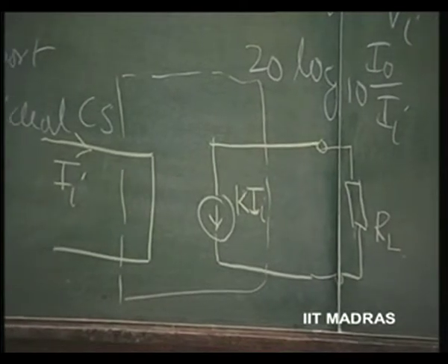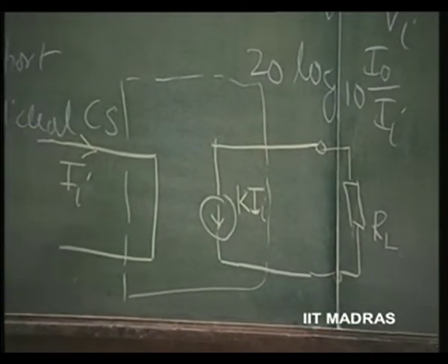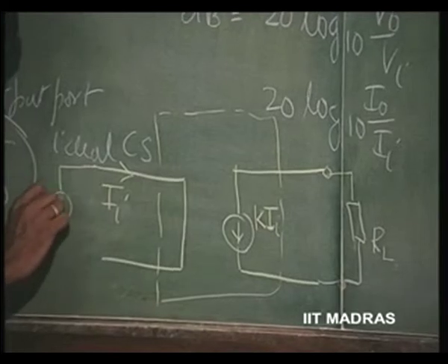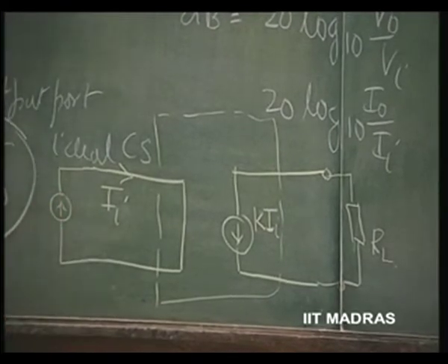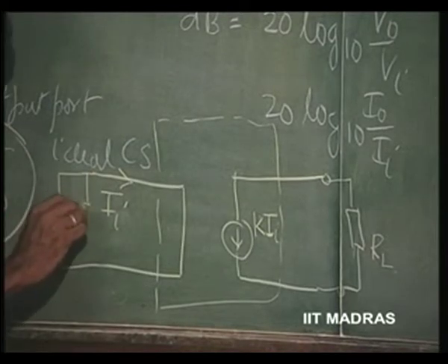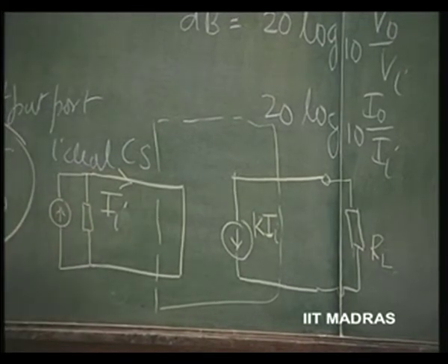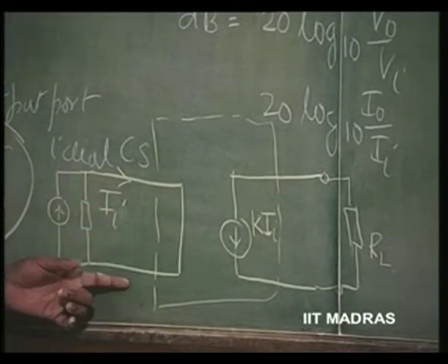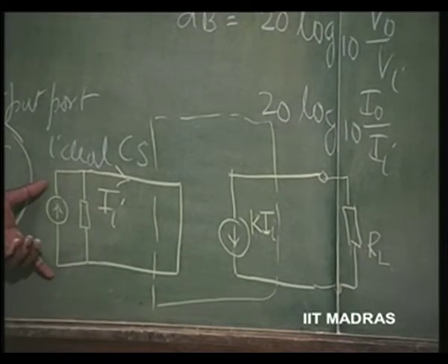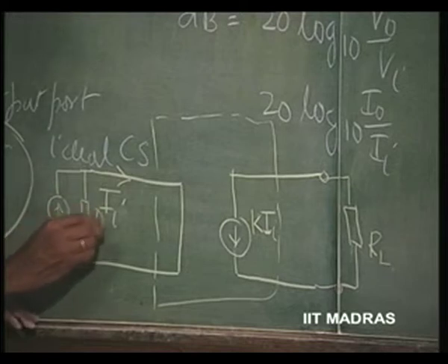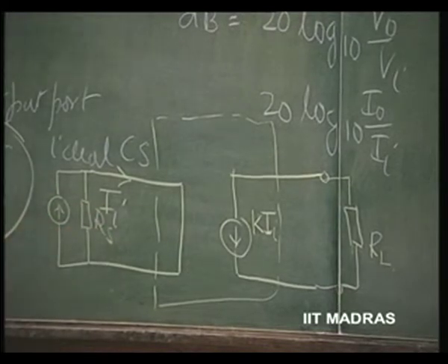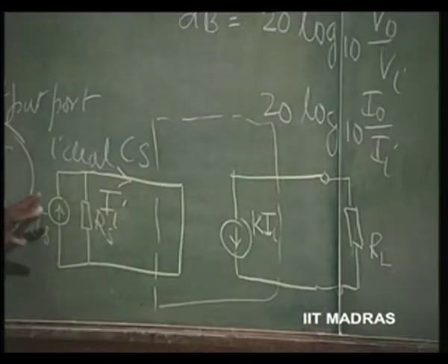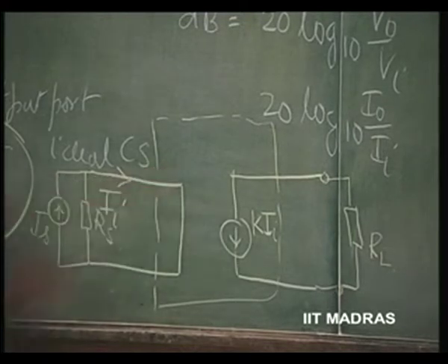Obviously, we must drive this again by a non-ideal source, whatever it is. So, we would rather drive it using current source, which could be ideal, or when it is non-ideal it can have R s. We will not use the other source, it cannot become ideal, because it is a voltage source, it will get shorted. So, we will use a current source which could become ideal with this going to infinity. So, this is the way we are exciting. This is the same non-ideal source I s shunted by an R s.